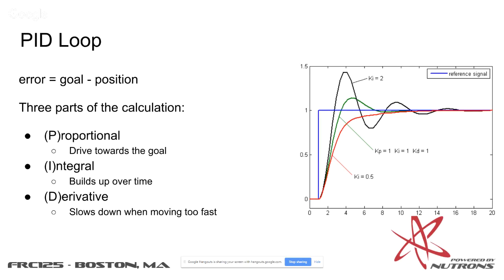This comes into use when you're talking about PID loops. The way PID works is that at any point in your system, as you're trying to reach a set point, you're going to have an error. Your error is your goal minus your current position. So if my goal is 10 and my position is 3, my error is 7. Based off this error, you're going to have 3 different terms. Your proportional gain: your error is 7, so you have a term proportional to that 7 that will make you move forward.